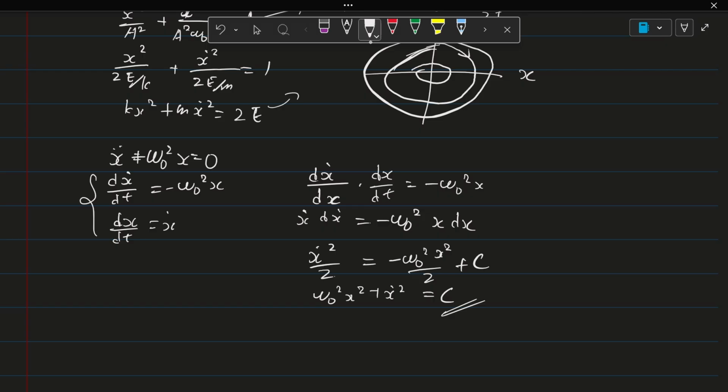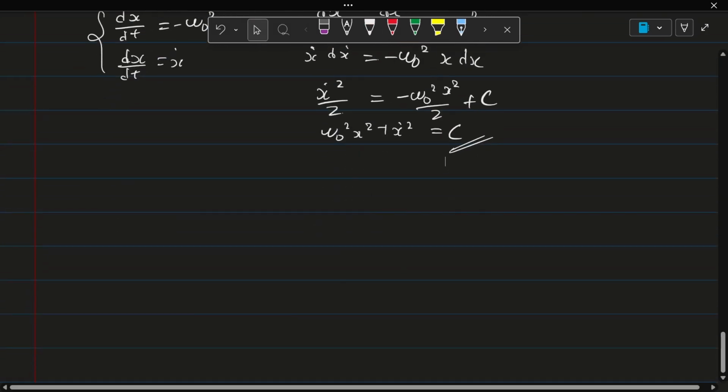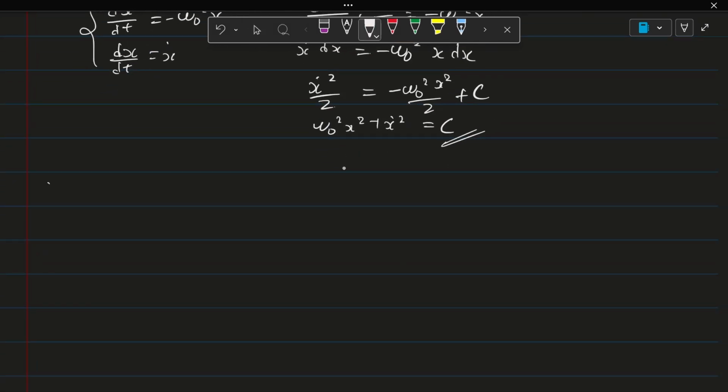We can now talk about the damped harmonic oscillation, or damped oscillation for short. So for a damped oscillation, the F would equal negative kx minus bx dot, the term that corresponds to the velocity. So therefore, you would get the differential equation mx double dot plus bx dot plus kx equaling 0.